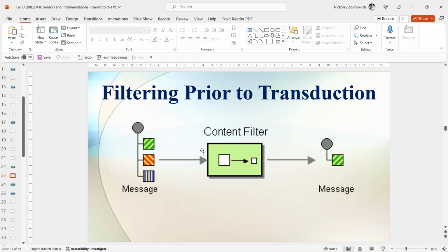The second is magnetically induced signal by a time-varying magnetic flux through the loop made up by the input signal leads. In this case, the error can be reduced not only by a shield made up of a material with a high magnetic permeability, but also by minimizing the area of the loop. This is done with leads close to each other, or, as we said, twisted.